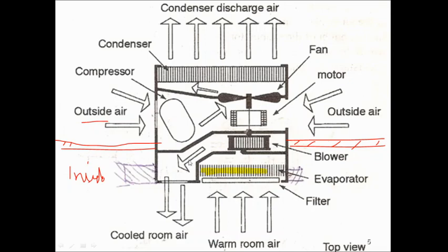So this system and this cycle goes on until the air reaches its set point. It is not that the air which passes through this cooling coil instantly comes to the set point. It will take some time. It may take say 20 to 30 cycles before it reaches its thermostatic set temperature. So we have to wait for that time period.